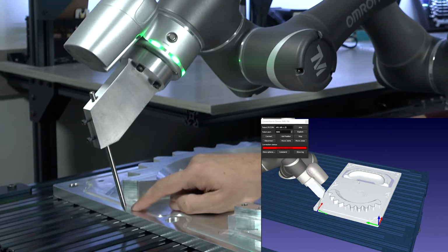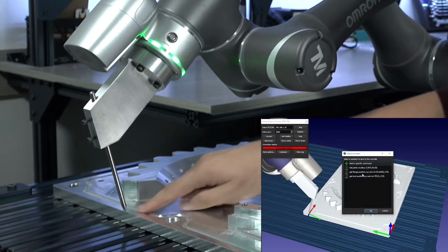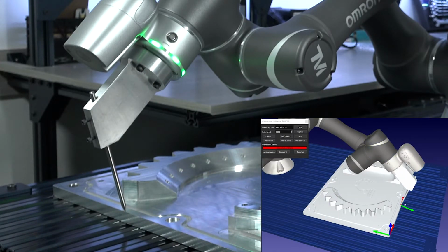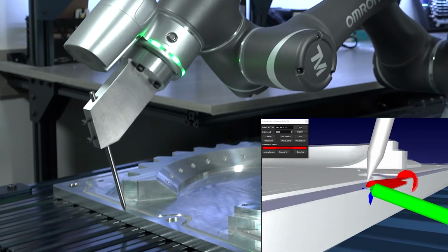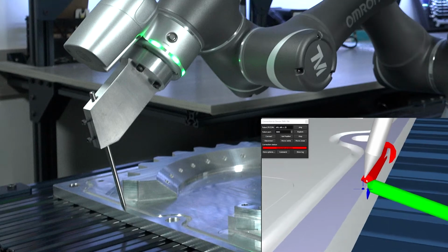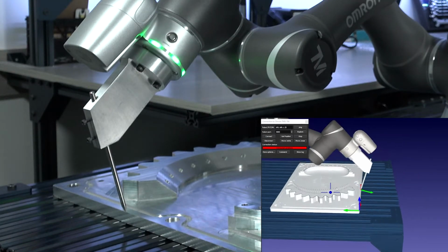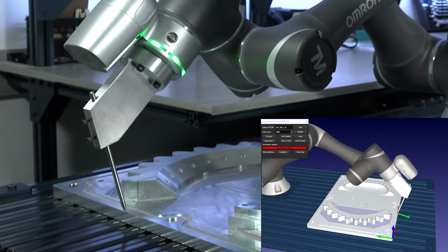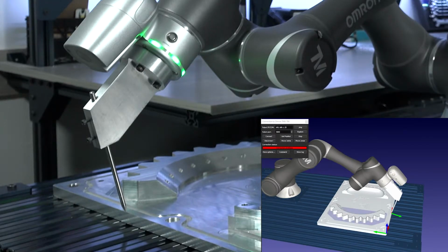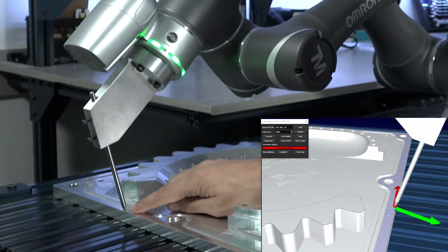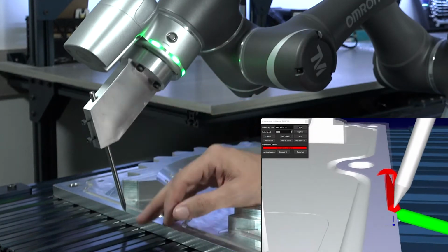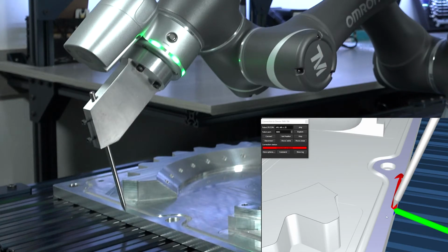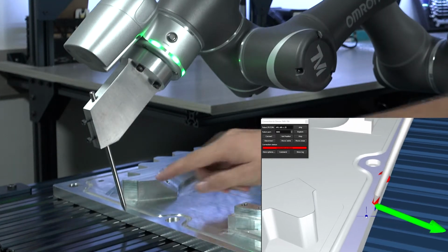So you can get the position and come closer and see that our TCP is pretty much on the edge. You shouldn't look at the actual 3D model of the tool at this point, because as you know, we redefined the position of this without any regard to the 3D model we had in RoboDK. So the Cartesian coordinates that you have in front of you are the actual position here.